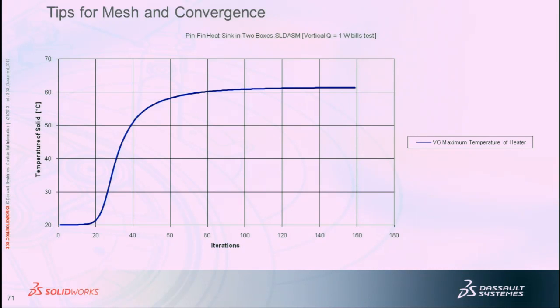What happens is, again, there are really only general recommendations for that. But really, you have to do trial-and-error type comparisons. If you're doing external flow analysis, let's say around a car body or a wing or something, what happens is, just like other programs, they have what's called a pressure-free boundary condition at the front. So if you have gradients that cross that computational domain with the pressure field that's assigned to that, it could potentially affect your results. It's kind of like a wind tunnel.